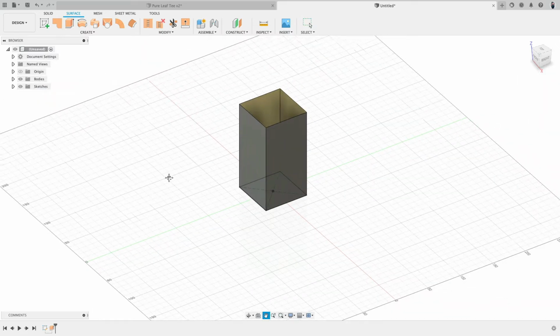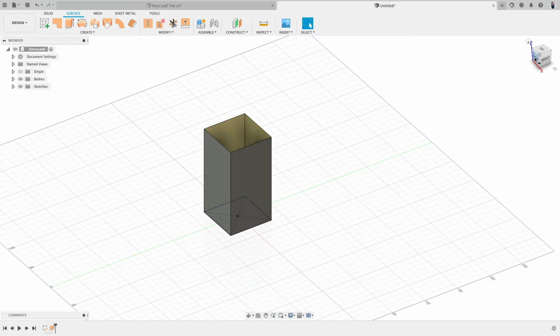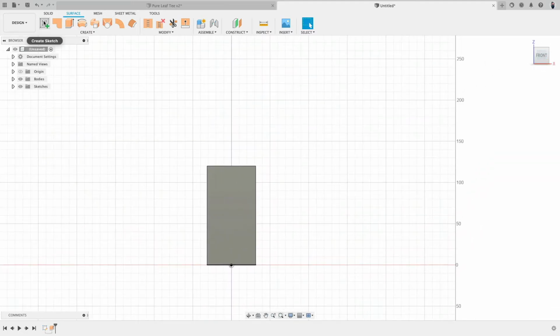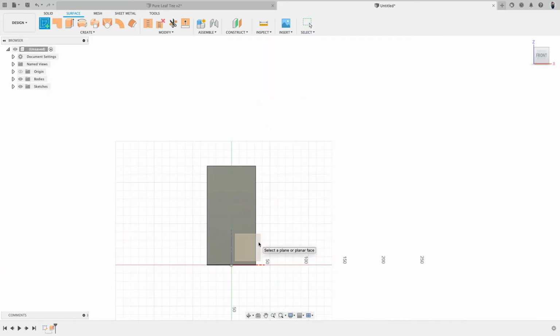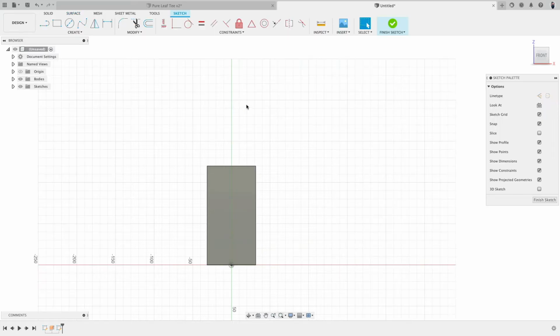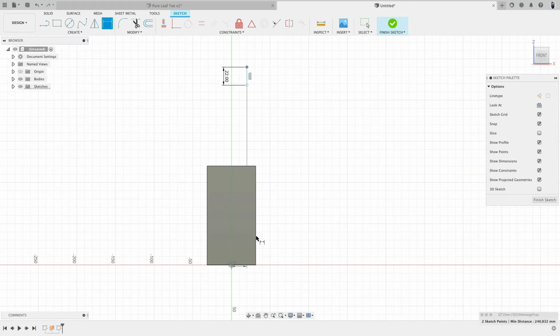120. Very nice. We also would like, at this point, to build the neck. Okay, new sketch. On the construction plane, we will draw somewhere a line, 22 millimeters. Very good. And then now we can dimension it. The inside diameter, or radius, is 17.